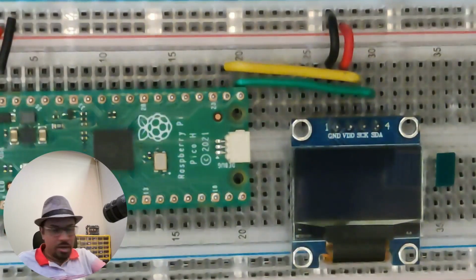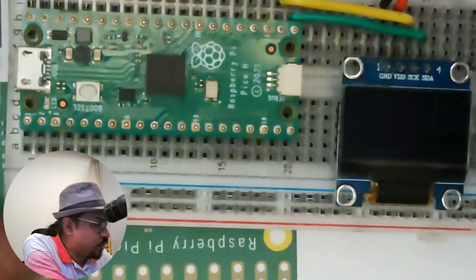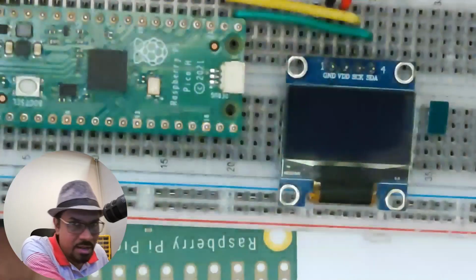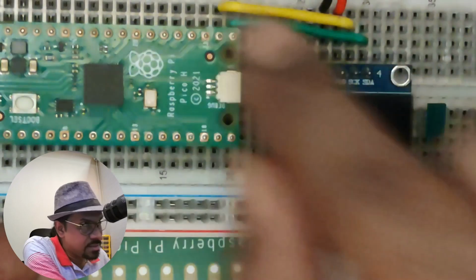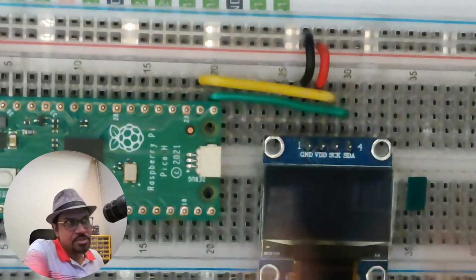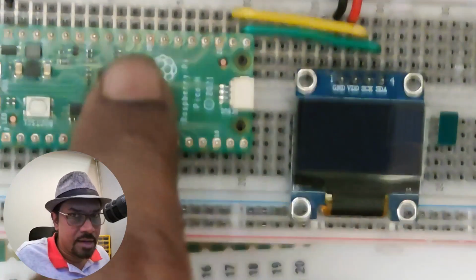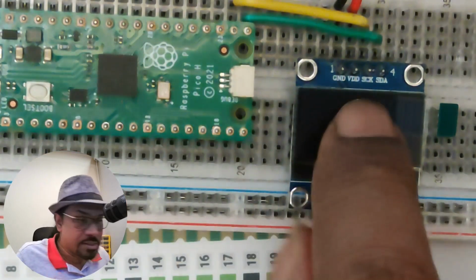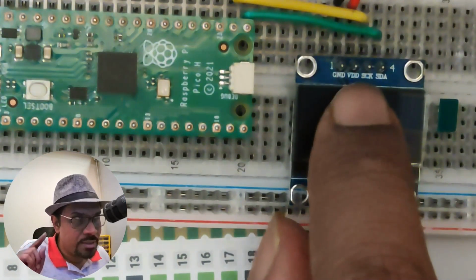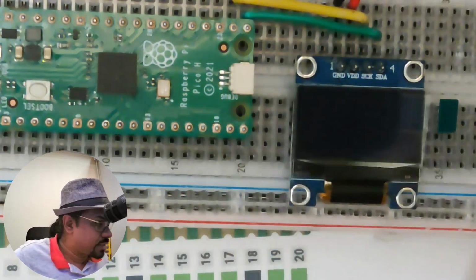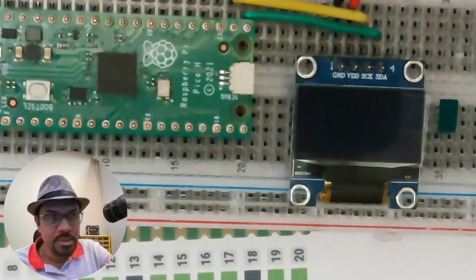But anyways, for now, I've just used the breadboard because it's nice to lay things on the breadboard, and you can add more devices and more sensors later on and improvise your circuit, right? And program it. So when you have this connected in this configuration, all the 4 pins are connected to the Raspberry Pi Pico. The next step is obviously installing the driver for this on the Raspberry Pi Pico, basically the library for this. As I mentioned, this uses an SSD1306, right? This configuration. So I'm going to use that library with I2C as such. So let me run this across.